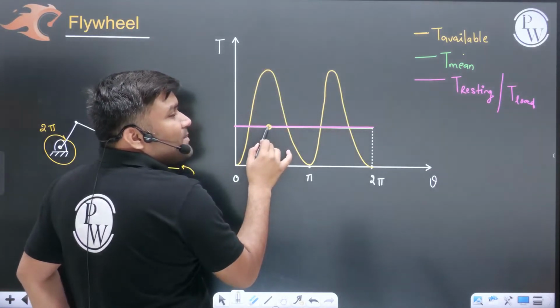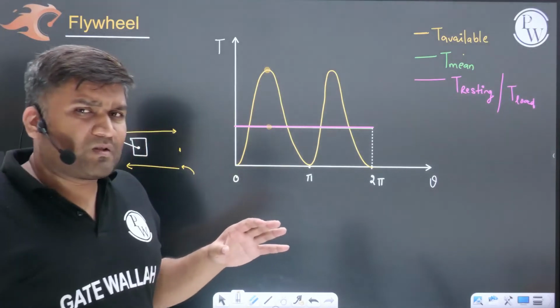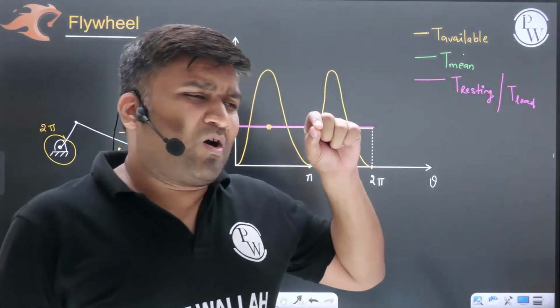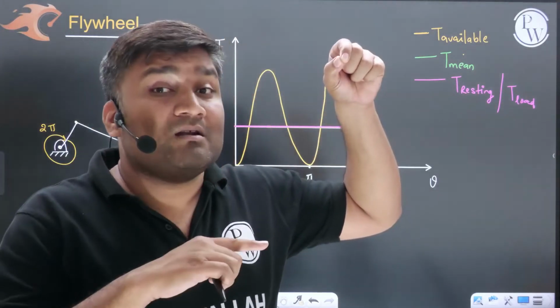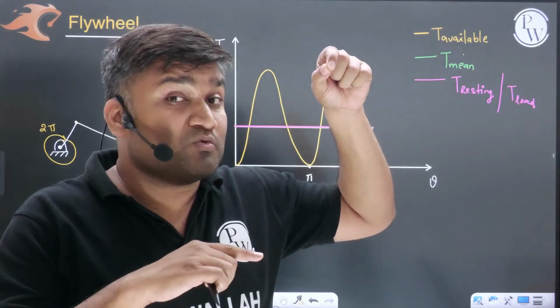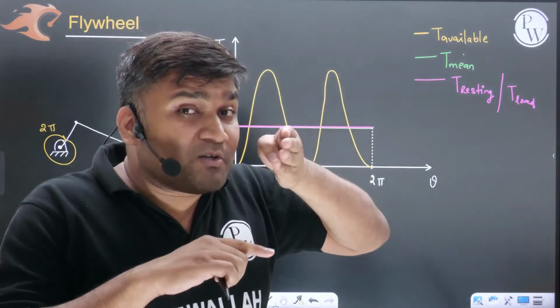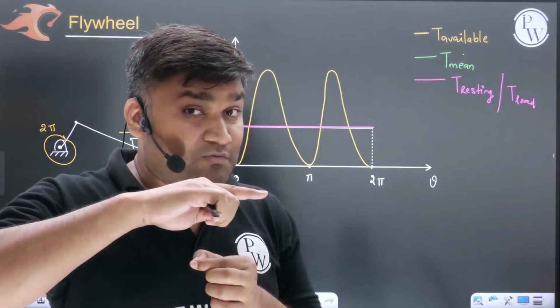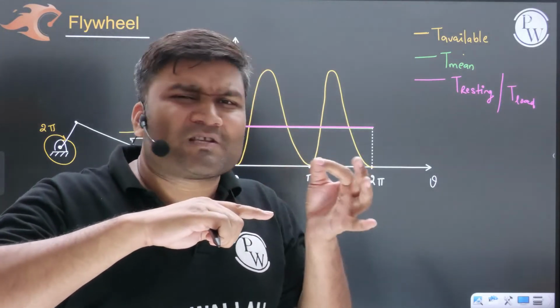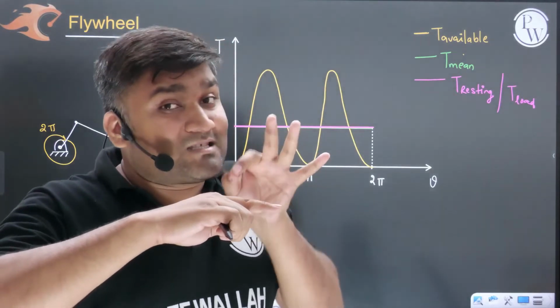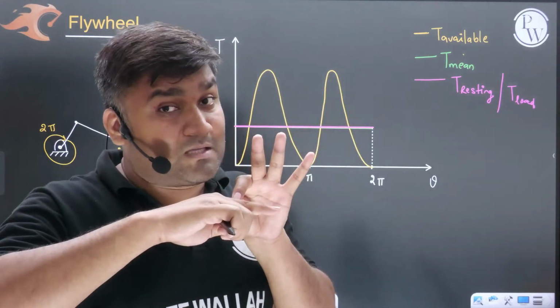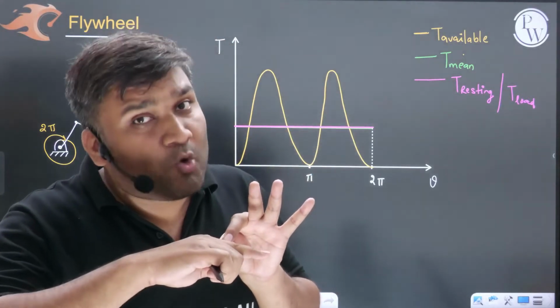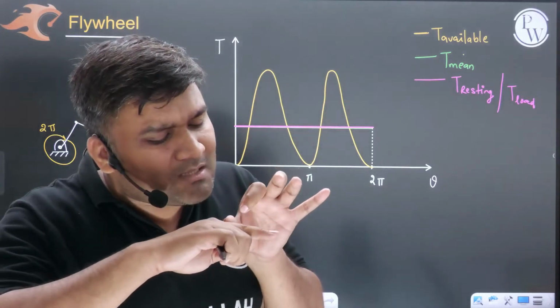So most of the time available torque will be higher than required, not of my use. Sometimes available torque will be less than the required, which is a trouble situation. Few situations may be there when exactly the same amount of torque is produced by the engine as is required by the load, only at these 3-4 points.